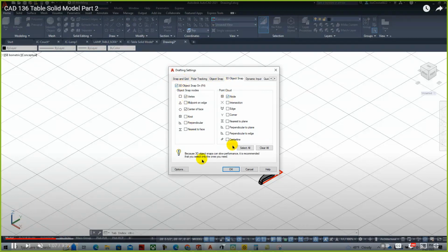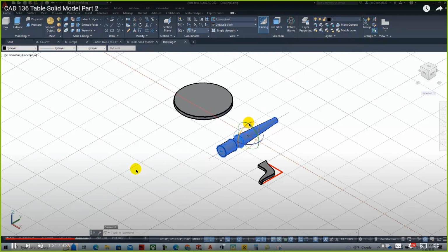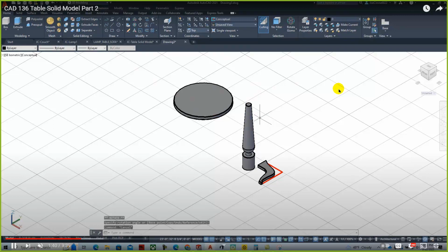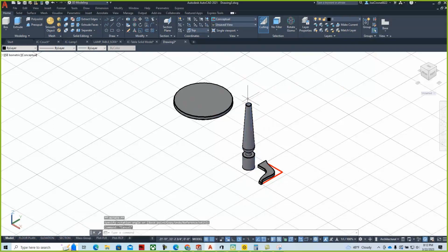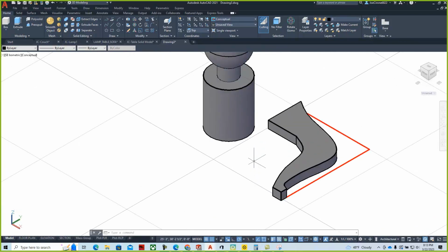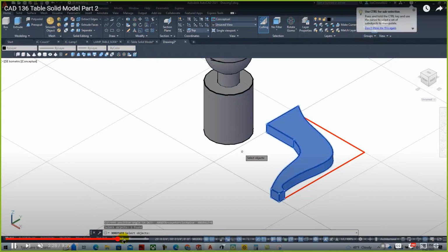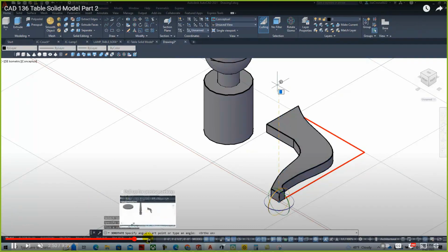Again, we set up our drafting settings, and then we'll use commands like rotate 3D. We'll use the 3D gizmo and the 3D move commands to start to navigate around in 3D space, because as you start to work with CAD, it's almost like working in space, where things will fly apart. There's no gravity. And so you have to pick them up and move them by known locations, which is what we use the O-snaps for. And so as we start to work with putting things together, we're always going to be gliding through and using these different object snaps and object tracking.